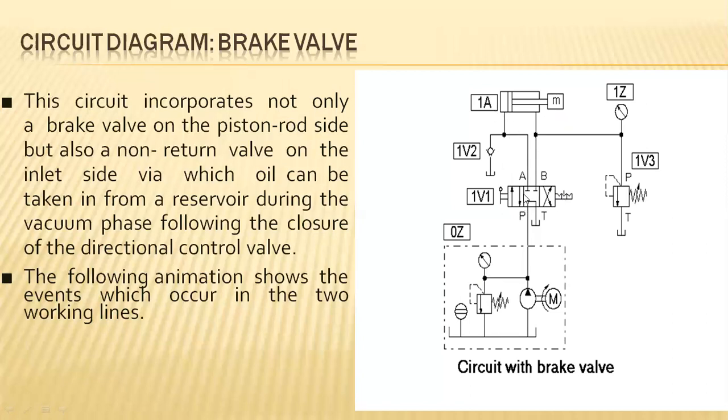And there are three different positions. First, the middle one is a null position, and when the lever is activated in the forward direction, the first position will come into force. When the lever is set into a return direction, this extension acts on the spring, and the second position will come into force.